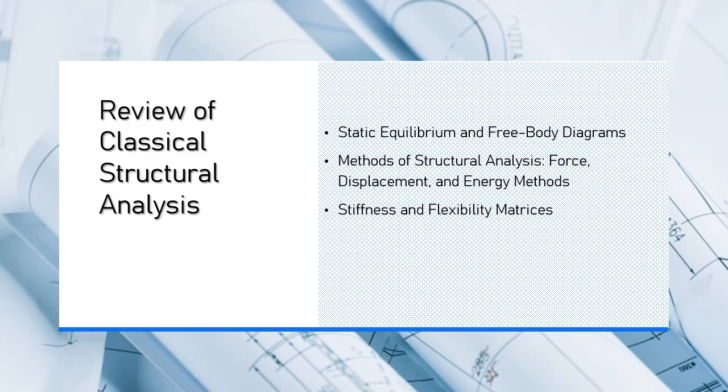3. Moment equilibrium. About any point, typically the origin or a support point. ΣM = 0, where ΣM is the sum of all moments, torques, about a chosen point. This equation ensures that there is no net rotational effect on the structure. These three conditions must be satisfied for any static structure in equilibrium. If any of these conditions are violated, the structure will experience movement or deformation.